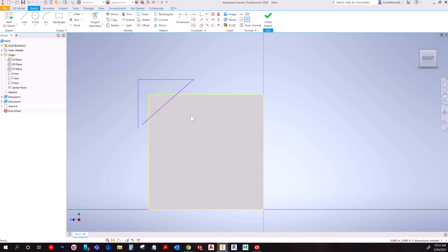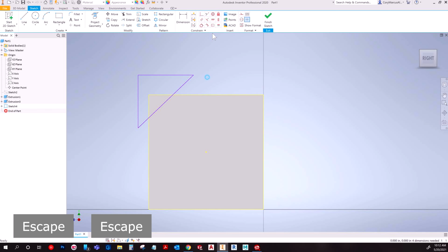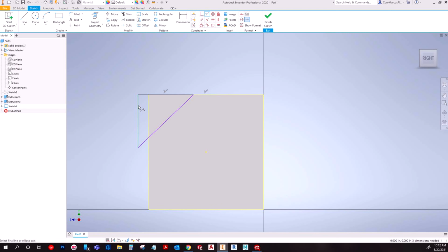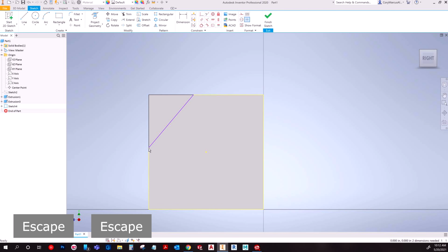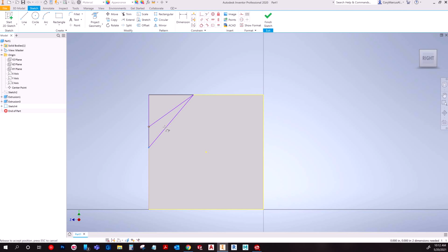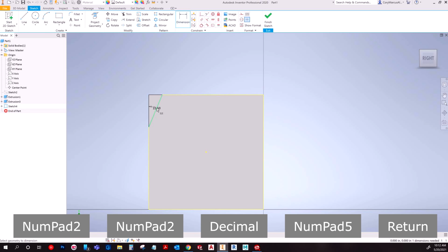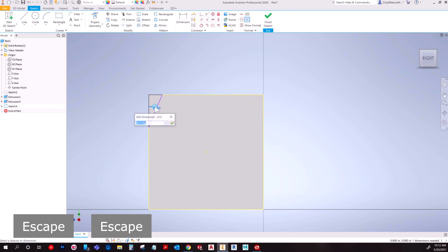And I'm going to use a coincident. I like to use the commands versus the actual pulling, but you can pull it. So collinear. Back to square one. So now when I pull it, it moves freely. And I can just go in and slap an angle, whatever I want, maybe 22.5, I don't know. Let's go ahead and do 45, though.